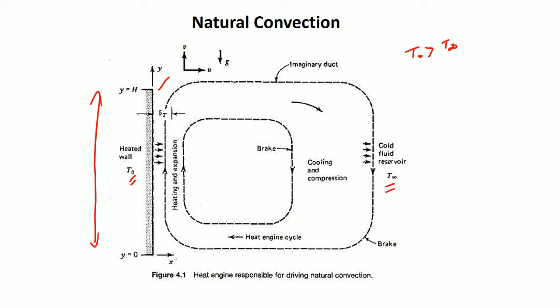Okay. So, the axis here, this is important, the direction perpendicular to the wall is x, whereas the direction along the wall is y, you can see it over here, the height of the plate is h. So, this wall is heated, there is a cold reservoir of fluid to the right side of it, right. So, the wall transfers heat to the adjacent fluid, as you can see what is given as delta T. We will come across what is delta T in a little bit, but the heated wall transfers the heat to the adjacent fluid, right.